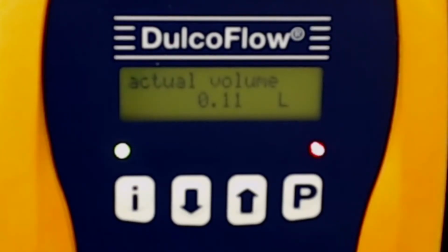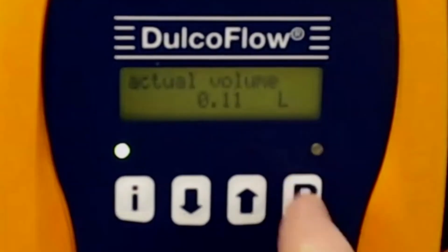Okay, so now we press the stop on the pump, and we advance through the process. So now it's asking you, is that what you actually drew down? So now we have to take our reading off of our calibration column, and we have to calculate that into the unit of measurement that we're dealing with.